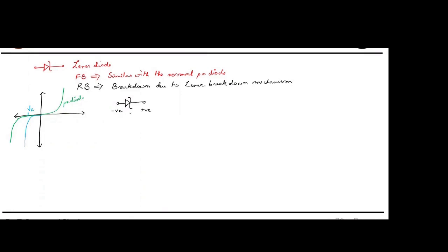Reverse bias. And suppose this voltage V is greater than or equal to Vz, then only under this condition, the breakdown condition, will this hold. Please try to note this. Whenever there is a problem related to a Zener diode, you have to check the voltage across these two points. It should be at least the Zener breakdown voltage. If this is satisfied, then you can replace the circuit like this.